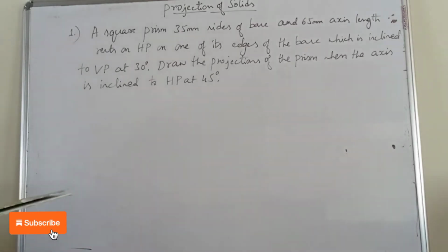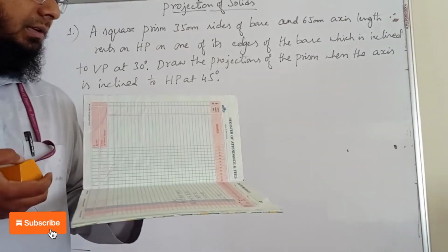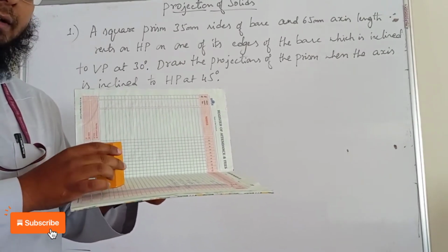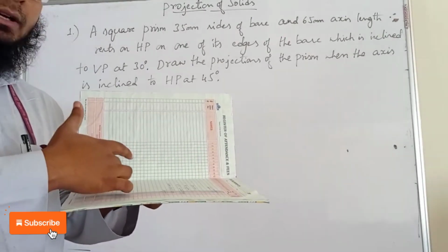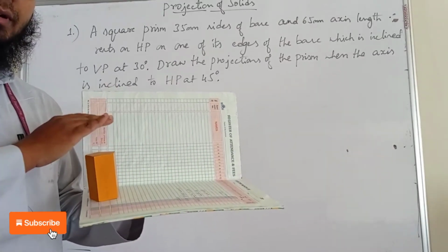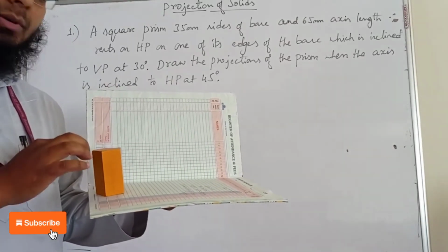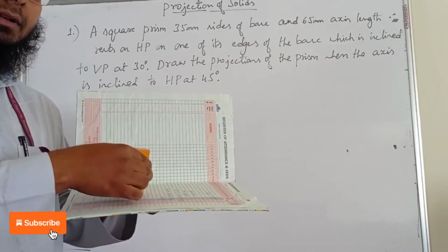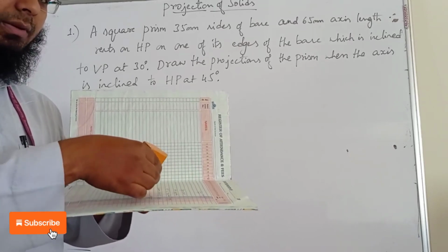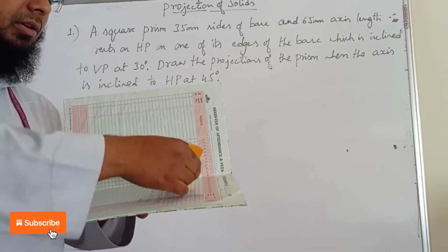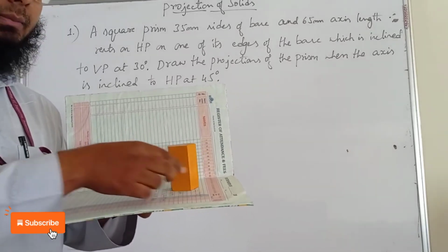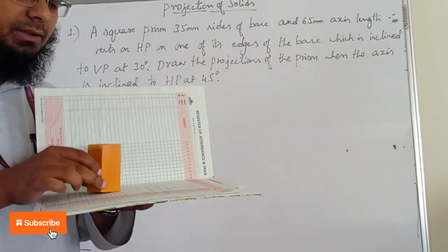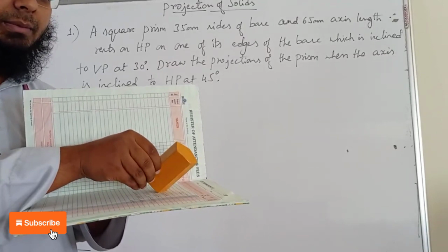So how the problem proceeds here, consider this is our first quadrant. This is our pentagonal prism, and I'm placing it with the right hand side reference, which means this side. First position, drawing the top view, front view. You can see that you have two faces, top face and bottom face. Second position, it is an inclination, right side inclination to HP, and then top view, front view. Similarly, inclination to HP was already given, so it is inclination to VP. So understood, right? First position, inclination to HP, then inclination to VP, like this.